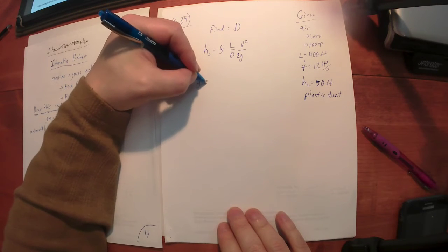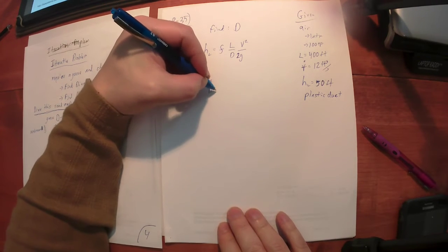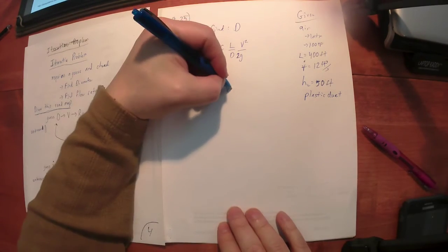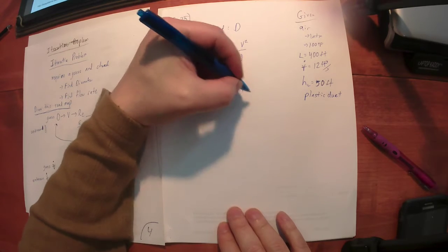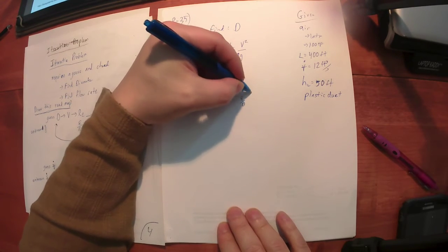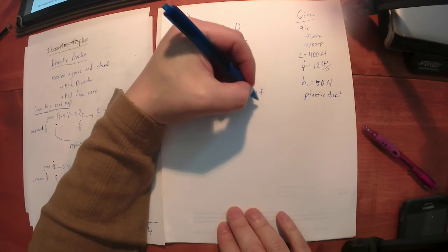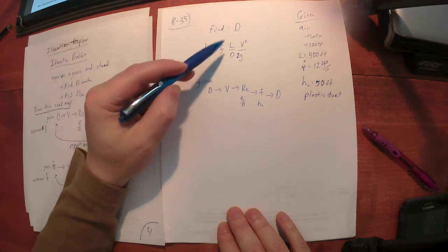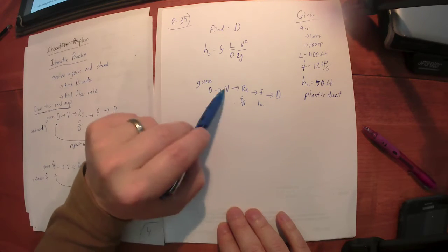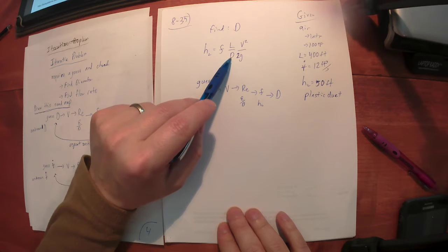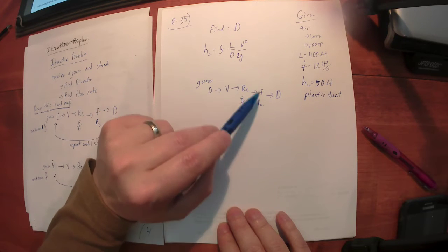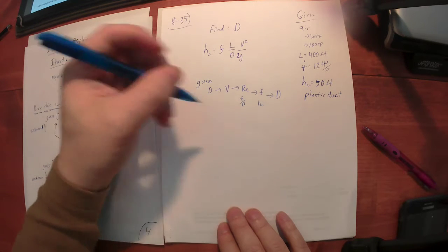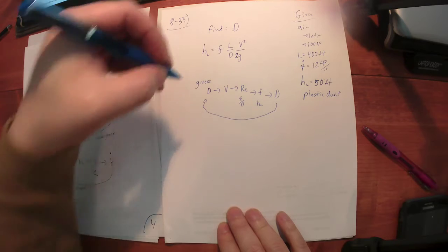I'm going to guess my diameter, use that to find a speed, use the speed then to find a Reynolds number. Using Reynolds number and epsilon over d, I can then find an F value. Using F and the head loss, then I can estimate, right? If I know everything else, and my diameter becomes my only unknown here, and I can use my head loss, which I know, and the Darcy friction factor, which I can base off of this guess, to find a better guess for diameter, and then repeat.